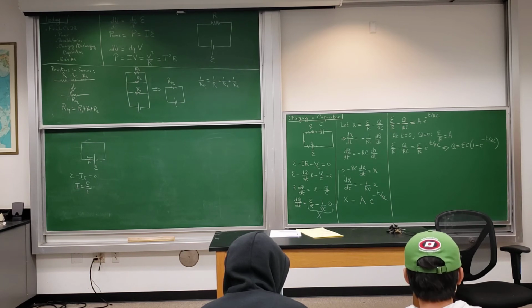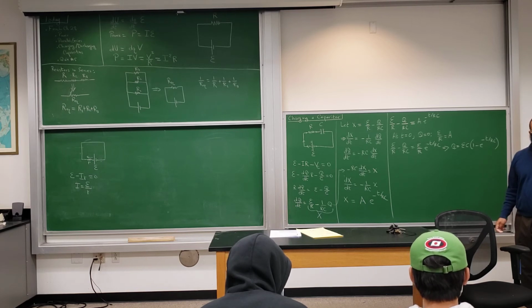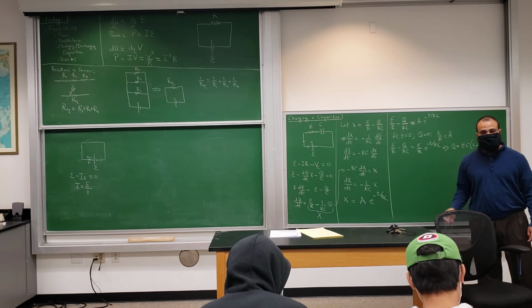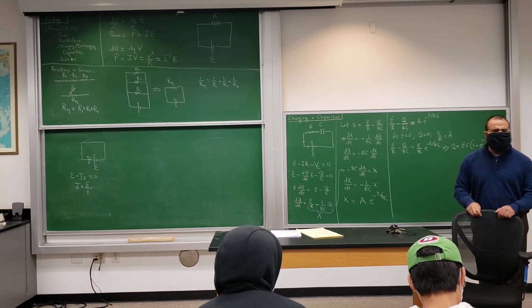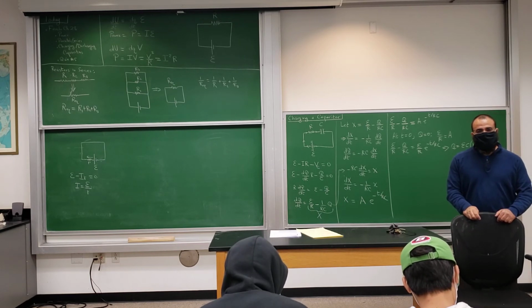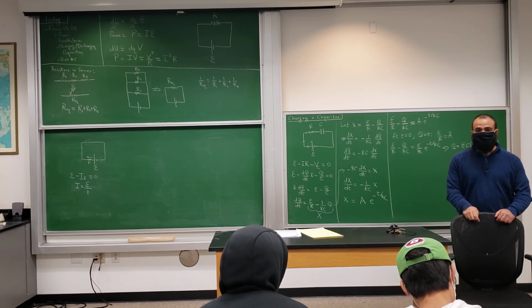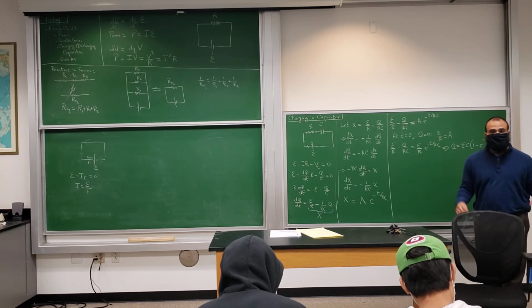Okay. At t equals 0, isn't C also equal to 0? No. The capacitance is geometric. It's epsilon naught, the area of the plates, divided by the distance between the plates. So capacitance is actually not 0. It's some number.